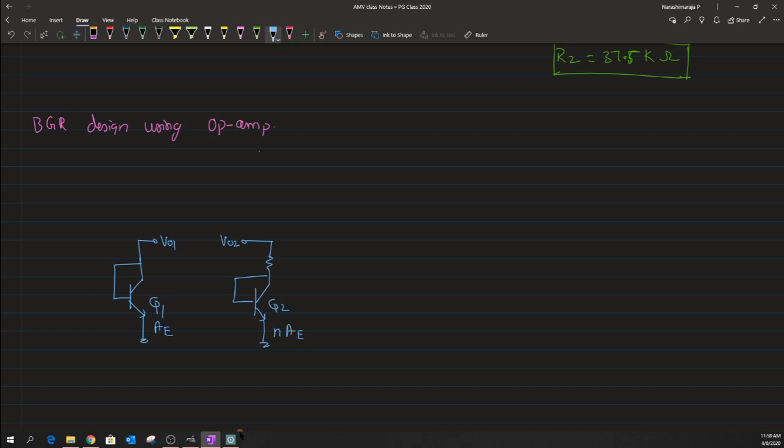And in order to realize the currents with voltage VO1 to be exactly equal to VO2, one has to ensure a kind of negative feedback circuit that is tapping the inputs right away from the node VO1 as well as the node VO2.